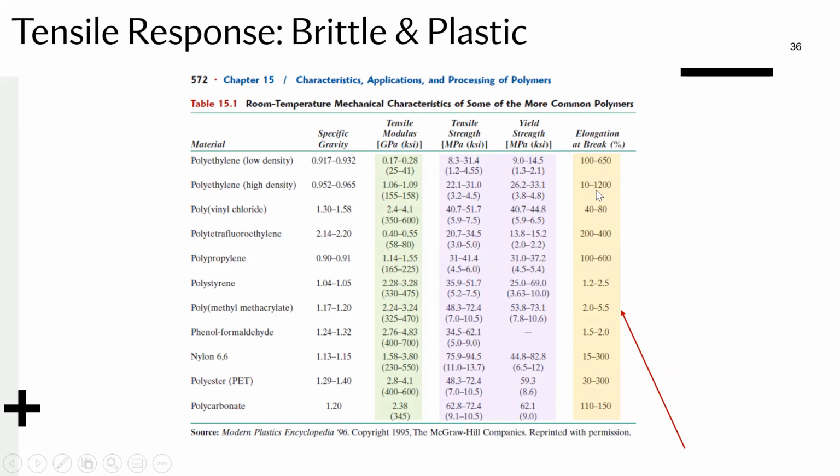Let's take one of these that has quite a lot of deformation. You can see that it doesn't really go beyond the yield strength. It actually drops even a little bit when it moves through that elongation region. So that's a plateau that I was talking about earlier: it reaches its yield strength, it starts that necking behavior, and then it never reaches a high stress amount. It just goes to a plateau and even drops in a lot of these cases.